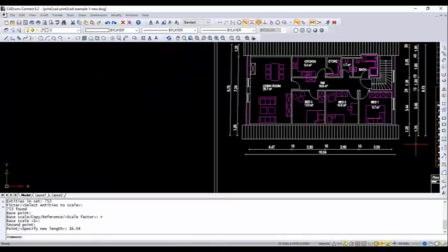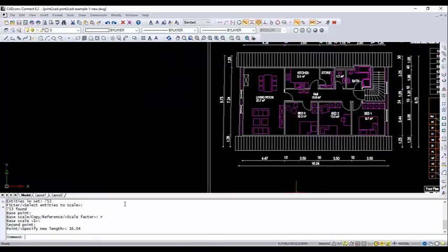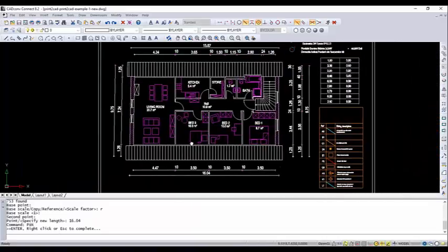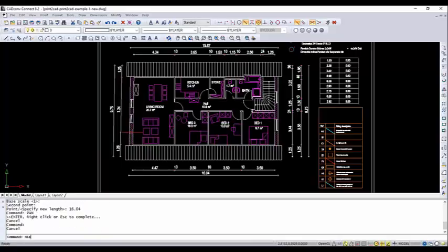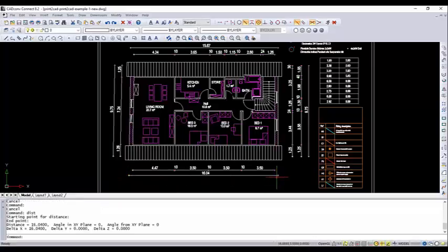So, and let me measure now this distance. Okay. Distance from here to here. Perfect. 60.04. Wow, good, yeah? And then you think, oh my God, now I have a perfect drawing. I can work with it. Everything is okay. Forget it. If you scale the drawing, you don't change the accuracy. Now what I did is I only made the drawing bigger, but not the accuracy.